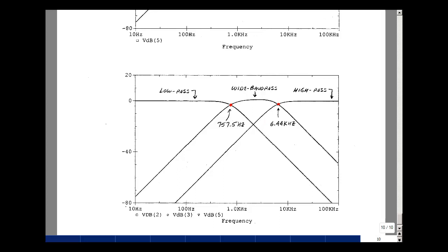So what's happening when you're listening to the music? Well, we took the music and split it up between the three filters, and now the three speakers are producing the sound. Now your ear acts as a summing circuit. So it's taking the signal from the woofer and adding it to the other signals, but these are very, very small because they're less than 0 dB. So you just hear the low frequency.